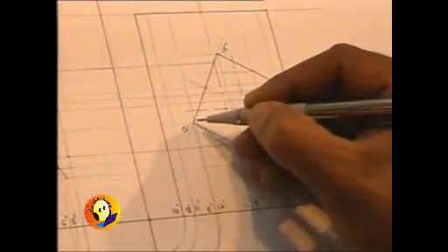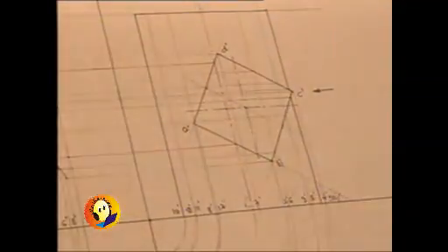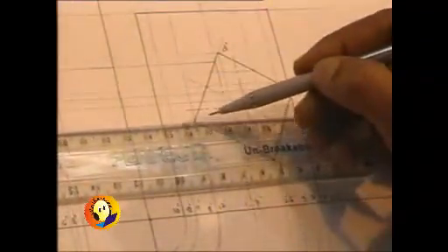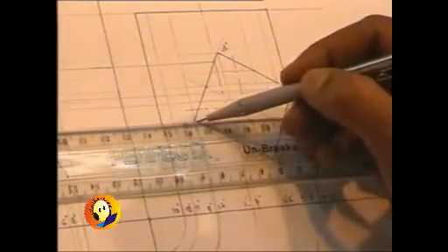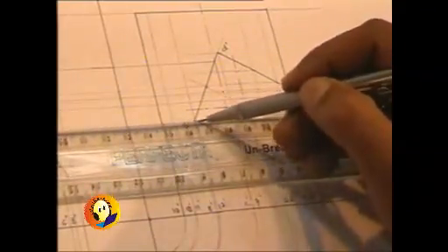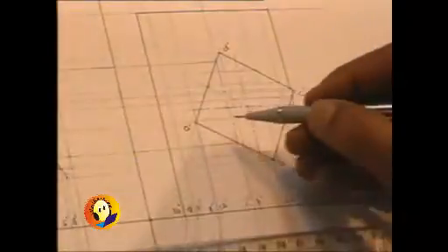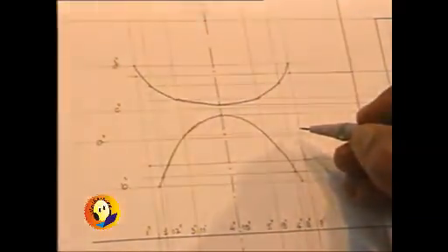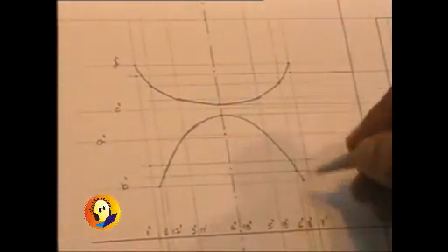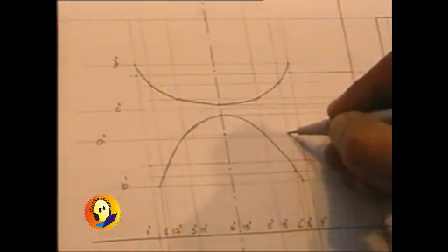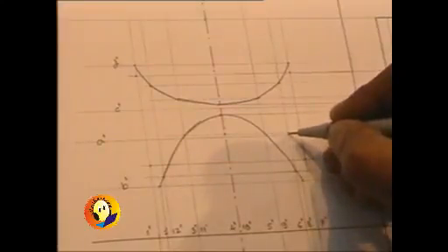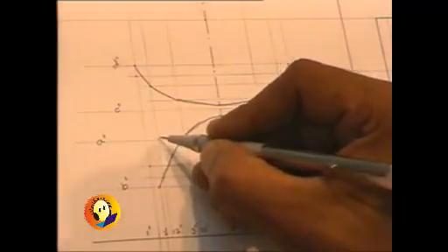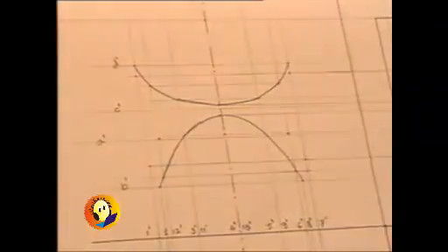We find that generator 8 and 12 is cut, but again those 2 points are very close to each other, and we will take help of the same generators which are present over here, and then we can mark the points on generator 8 and 12. They belong to actually generator A only, and similarly over here 8 and 12.